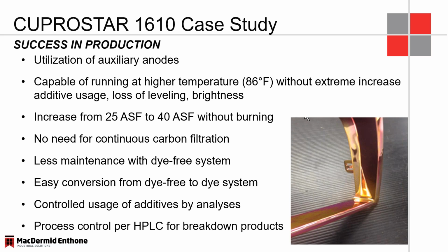We eliminated their need for continuous carbon, and they have seen a lot less maintenance. So, I indicated the tank walls are a lot cleaner. The anode bags are a lot cleaner. So they were able to really reduce the amount of maintenance and cleaning that needed to be done on the system. One of the advantages of the CUPROSTAR family, the 1600 to the 1610, is that I can easily go